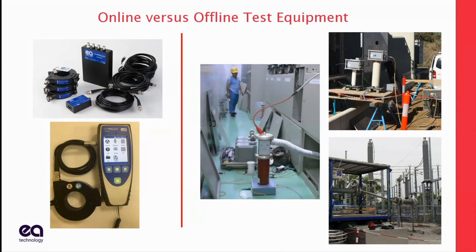The cable needs to be at line voltage or even higher, and so you need to bring in equipment capable of doing that. Typically that's done with VLF test sets. They're big. They can be man portable for up to say 30, 50 kV, but beyond that, we're talking truck mount.